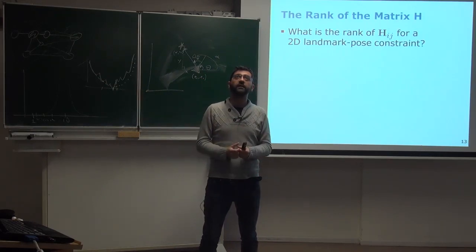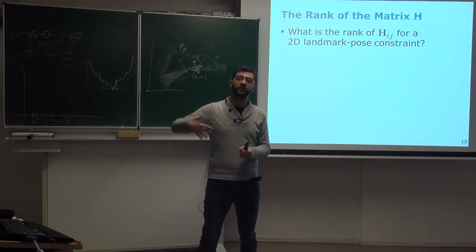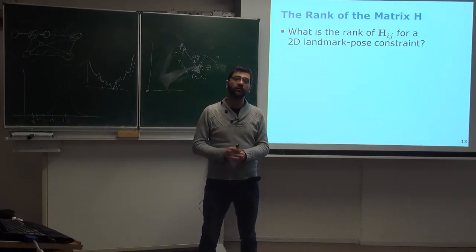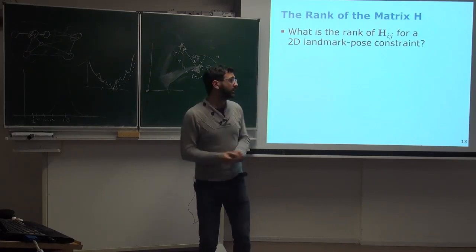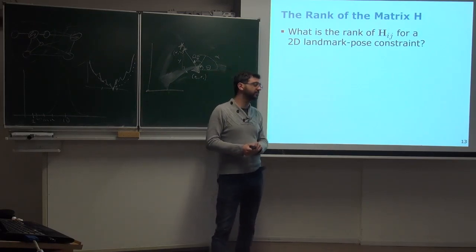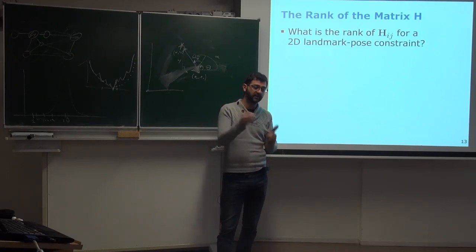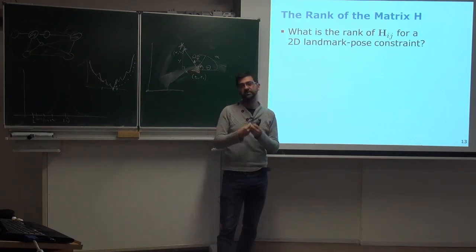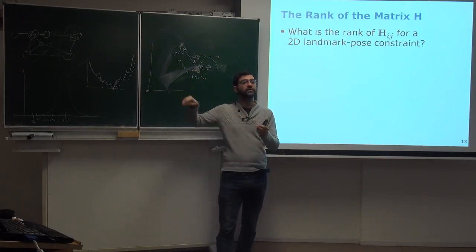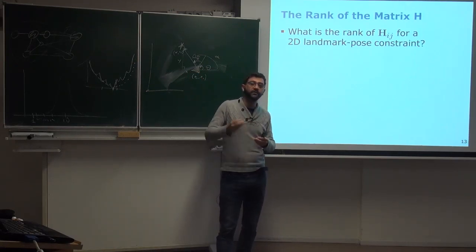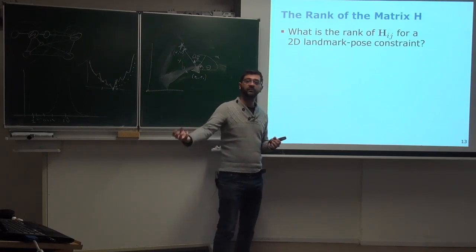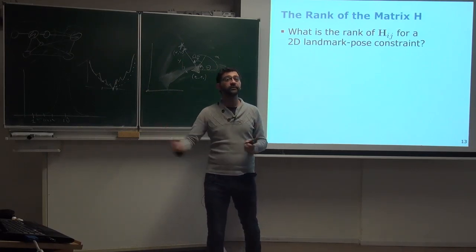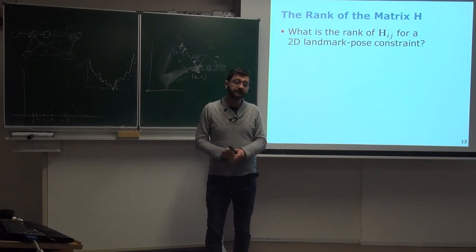So we need to include additional constraints or additional regularization terms on our optimization problem. Regularization terms basically means we need to pick, in the space of infinite solutions, some solution that we like, which can be the solution of minimum norm, closer to something that we know, or considering that one pose is always at 0, 0, 0. That's what we're doing for graph-based SLAM.